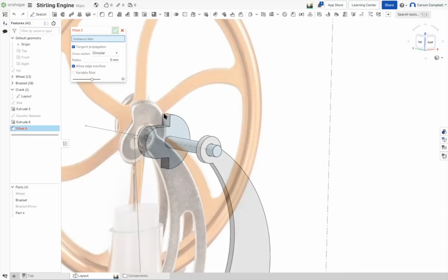But the guy that has to edit that model later on, and he double clicks that feature, and there's 200 dimensions in there, you can't double click a face on a model and have the ability to make a change. Your design intent is messed up. It's not a good practice to put 1,000,000 dimensions inside of a sketch. The next guy's going to hate you.